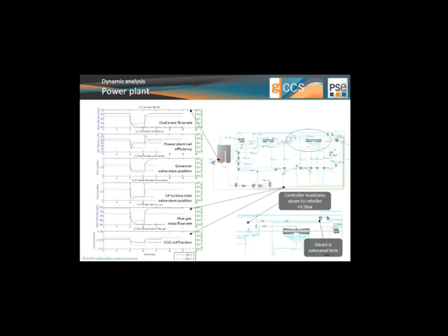This LP turbine inlet valve was used to maintain the steam requirement to the reboiler, which basically said that we needed at least 3.5 bar absolute to be delivered to the capture plant. So whenever we see that this might drop, this valve will quench the flow to the low pressure steam section. This is exactly what we see here.